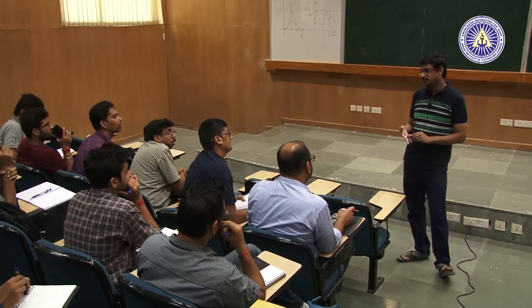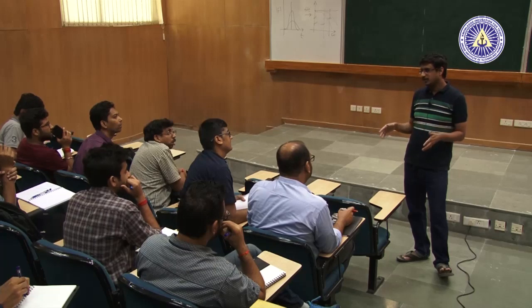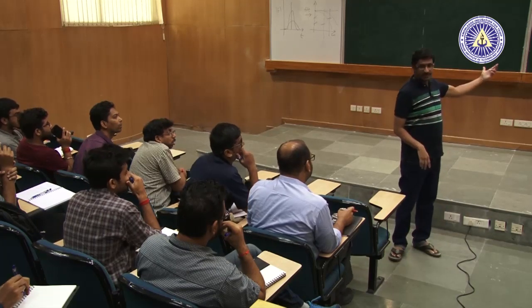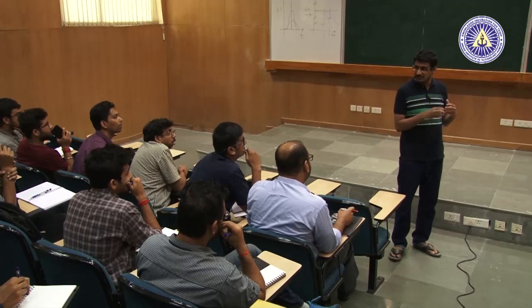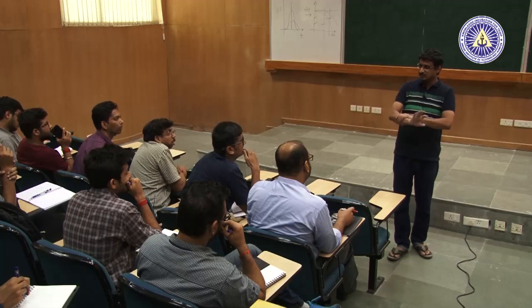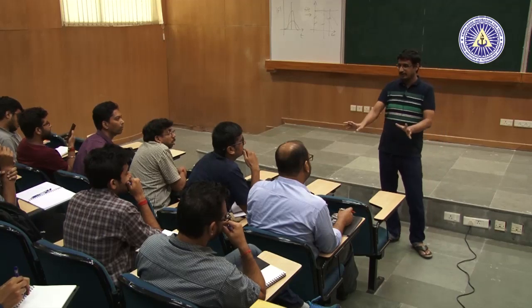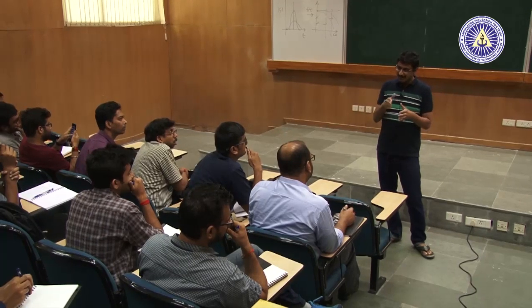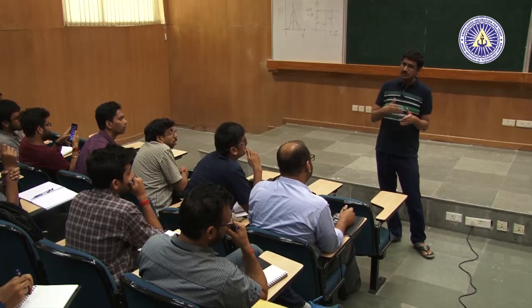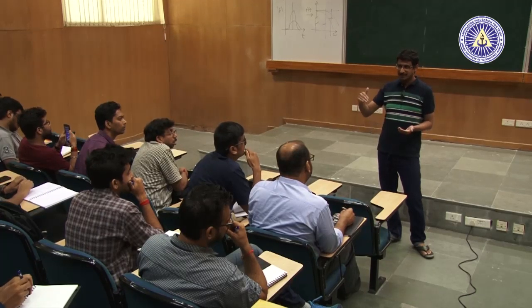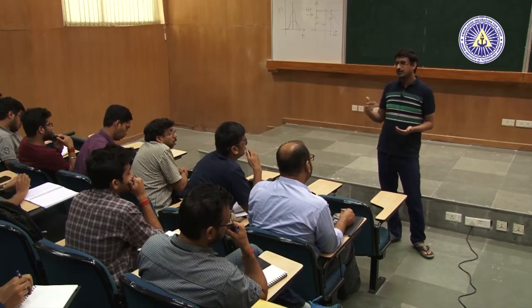If your objective is to look at the spectral content, then you choose the number of samples in such a way that on the discrete spectrum you are at least covering the required range. If you take Fs equal to say 300, then Fs by 2 will be whatever that value, and if you take N as the number of samples, then the resolution in the DFT will be Fs by N, so 300 by N.